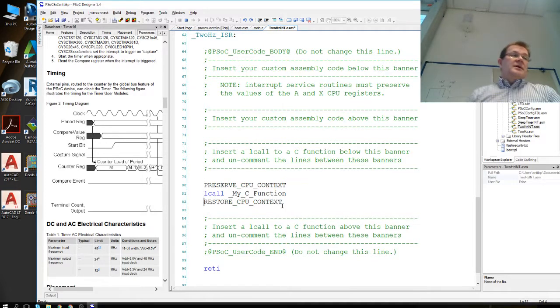That helps bookkeeping of the most important register values, since you don't know at which point this is interrupting. It can be in the middle of calculations. So you must make a copy of all the register values so that you can return back to where it was when the interrupt happened.